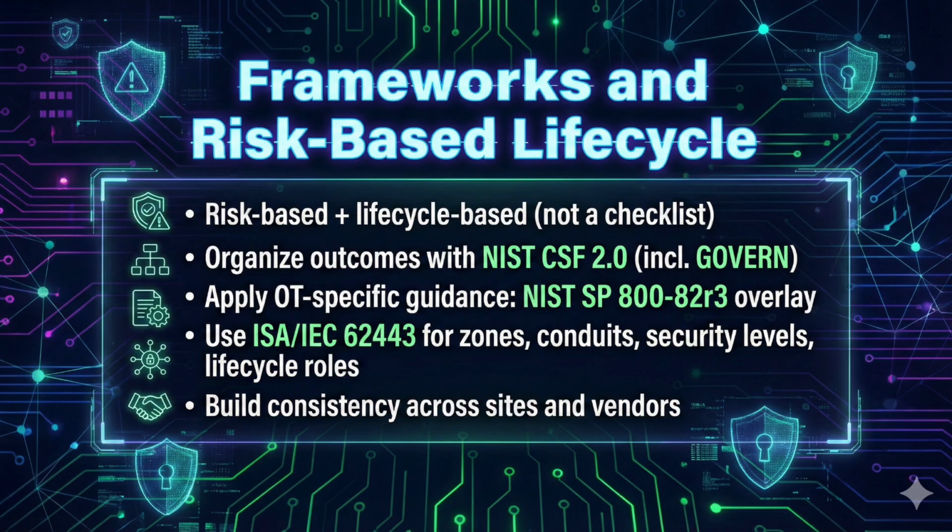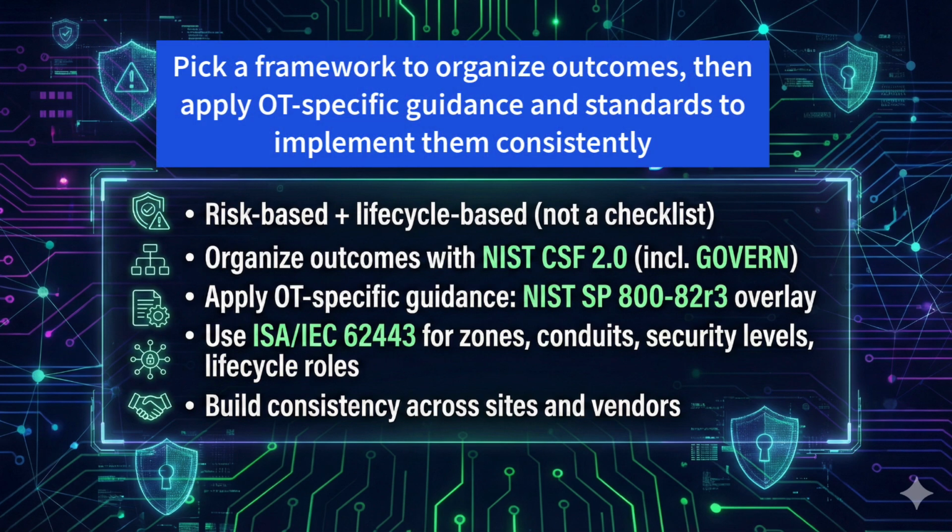Finally, ISA/IEC 62443 is the standard many OT organizations use to define requirements across the lifecycle: asset owners, system integrators, and product suppliers. You'll hear terms like zones and conduits, security levels, and secure development lifecycle, and we'll use those concepts throughout the rest of the lesson. If you remember one thing, pick a framework to organize outcomes, then apply OT-specific guidance and standards to implement them consistently.